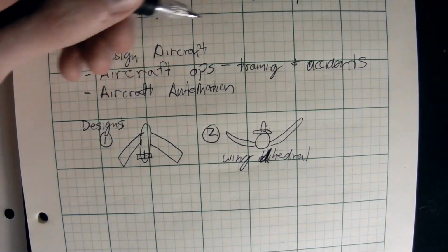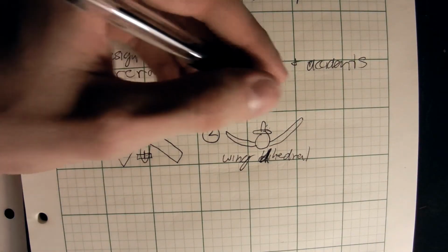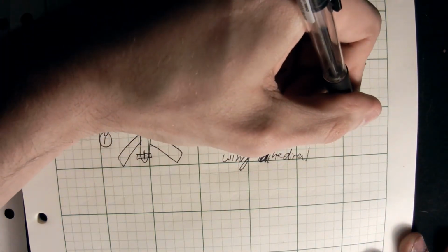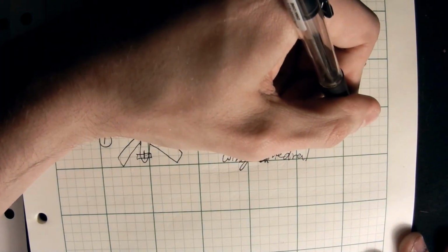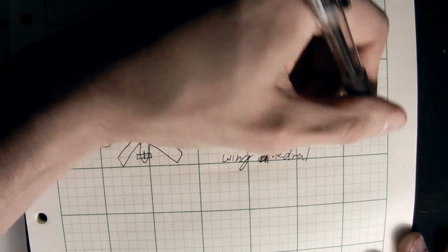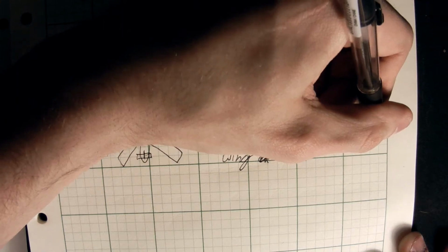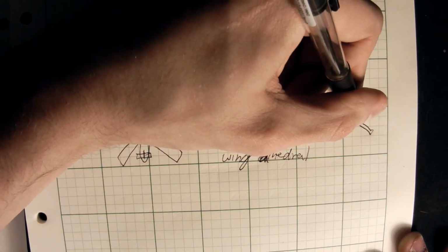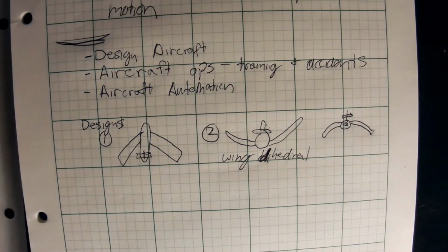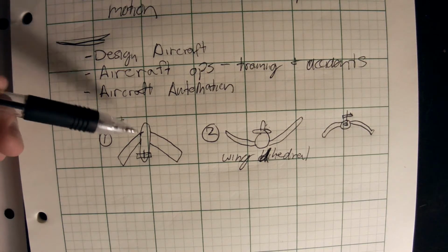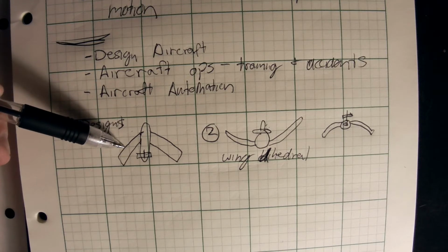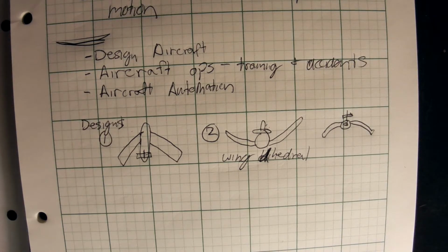And as you might also be thinking, if it goes the other way, it looks like this. It looks almost like a spider. That creates an unstable equilibrium, and it wants to be tipping. You might be asking, why would you ever want to do that? Well, sometimes if your wings are swept back too much, you might create so much stability that it's almost impossible for it to turn, even when you're trying to intentionally turn it. So you might have to add some unstableness.